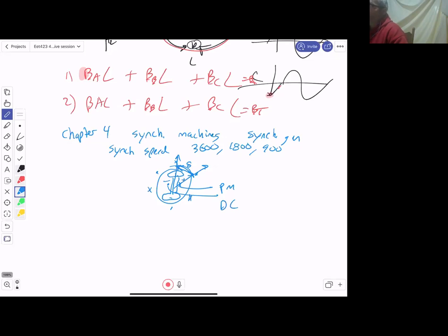So that's why, if we had an opportunity, and I was trying to get us a tour of Maine Independence Station, they have these very large devices called load commutating inverters, which are basically a fancy way to say adjustable frequency drive. Their gas turbine generators, you can't just run natural gas and start them, because they have to be out of the flame path for a period of time before they back in, otherwise they'll melt. So they actually run their generators as motors to get the synchronous machine up to a certain speed before they turn the gas on. So that is a case where we have a generator normally, but it actually operates as a synchronous motor, and the machine doesn't care at all.